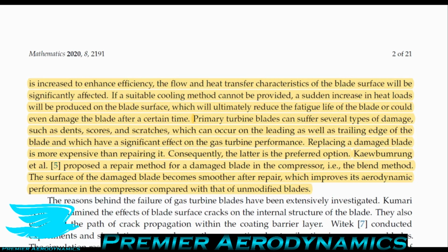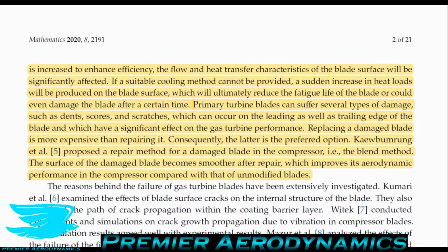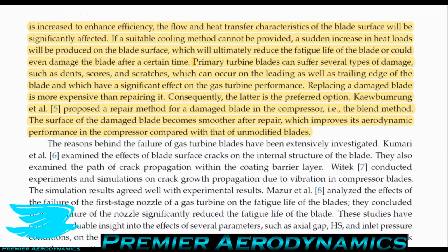Let's go on to, there's a method to repair these damaged blades in a compressor, for example, i.e. the blending method. And this actually results in the damaged blade becoming smoother, and it increases the aerodynamic performance compared to the unmodified blades. However, this is for compressors and not for turbines, I guess. The difference between a compressor and a turbine is that compressors add energy to the flow, turbines take energy out. That's a very easy way of thinking about it.